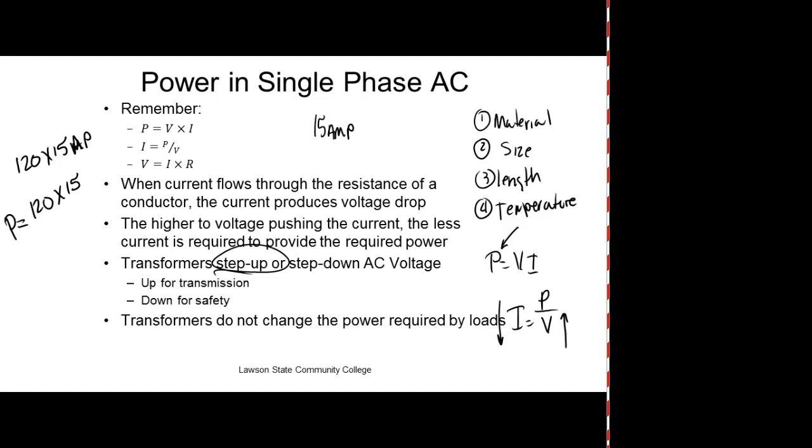Now the breaker doesn't see watts, the breaker sees amps, because the breaker doesn't drop any voltage. So it doesn't see watts, right? You understand? Breakers are not supposed to get hot. If you've got a breaker that's getting hot, what does that mean? That means it's dropping voltage and you need to do what? You need to replace it. And it will trip at a lot lower current too. So breakers don't get hot.